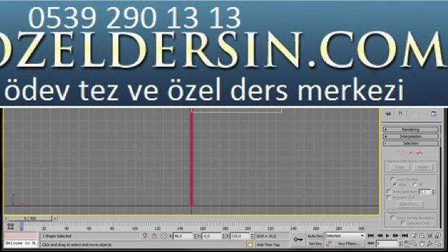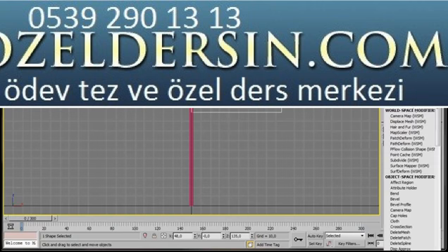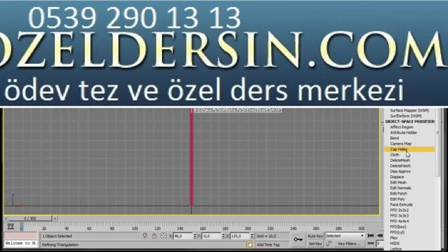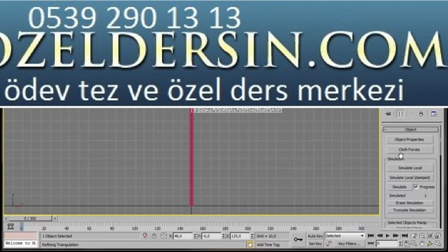First of all, we'll turn off our Editable Spline. We'll scroll down and look for Garment Maker. Now look at that, Garment Maker has just converted the 2D spline into mesh. Let's go over to the main parameters, and in density, we'll just boost the density up a little bit, something like 0.27. Now we can go back to the Modify list, or scroll down, and we'll select the Cloth Modifier.